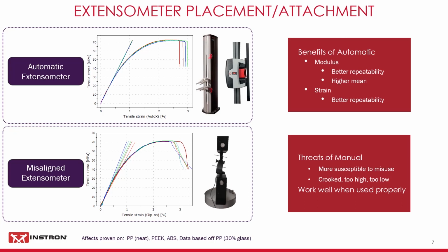As a result, we were able to get very consistent modulus data, which you can see by the very tightly grouped modulus lines. Then we ran a study using a clip-on and intentionally attached it at an angle. As you can see, with a poorly attached clip-on, you can expect more variability in modulus data and inconsistencies in your break